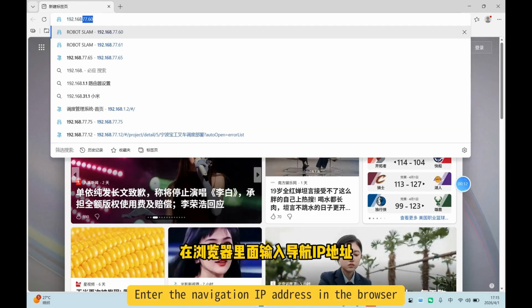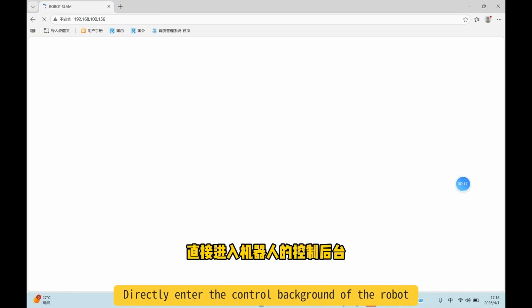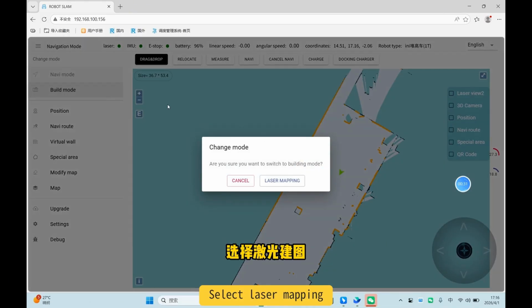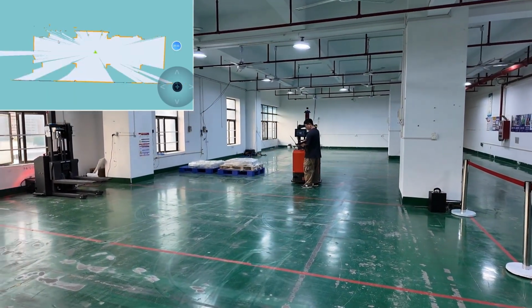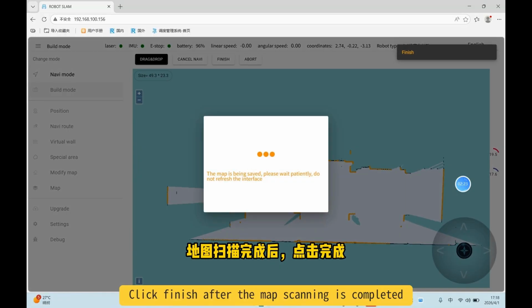Enter the navigation IP address in the browser. Directly enter the control background of the robot. Click the mapping mode in the left sidebar. Select Laser Mapping. Click Finish after the map scanning is completed.